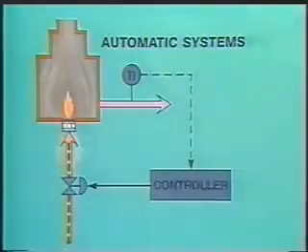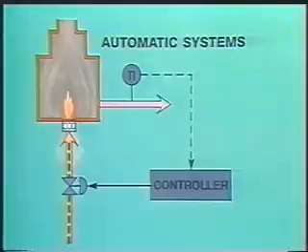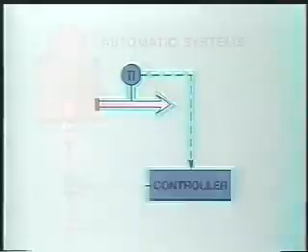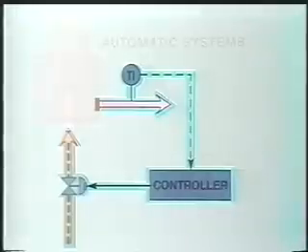Let's consider an example. In an automatic system, the controller adjusts the fuel flow to the burners based on the outlet temperature of the charge. Now, if the measuring or transmitting instrument sends out a faulty low temperature signal, the controller will automatically increase the flow of fuel to the burners, trying to compensate for the apparent decrease in outlet temperature.